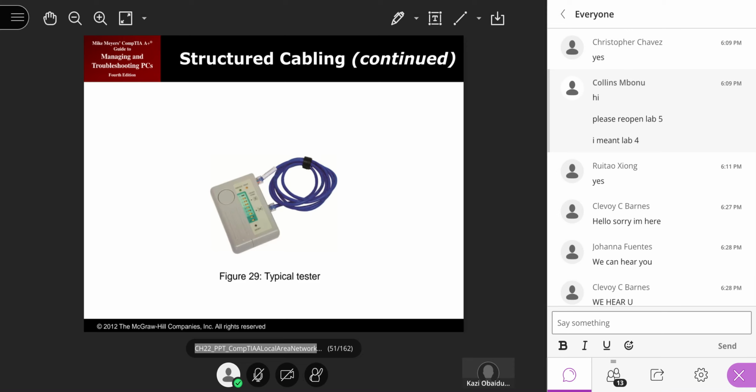So this is the thing, typical tester. Okay, after designing this one, then we have to test it. Is this cable okay or not? Is any fault developed or not? Is any cable mixed with the other one or not? Okay, that we have to test. After test, if you see all green signals for all the cables, then this cable is ready to use. Okay, we designed, we built something, and then we have to test it.